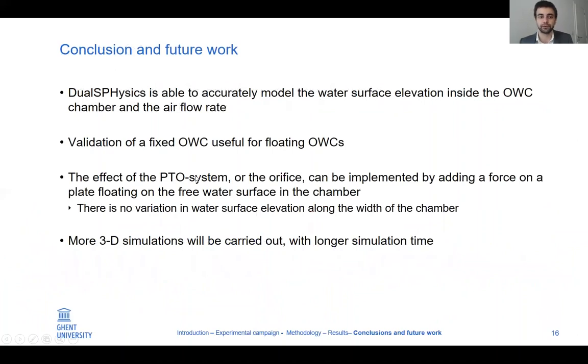So now some final conclusions and future work. As you could have seen, DualSPHysics is able to accurately model the water surface elevation inside the oscillating water column chamber and also to accurately model the airflow rate. Validation of a fixed oscillating water column is useful for floating OWCs in the future.